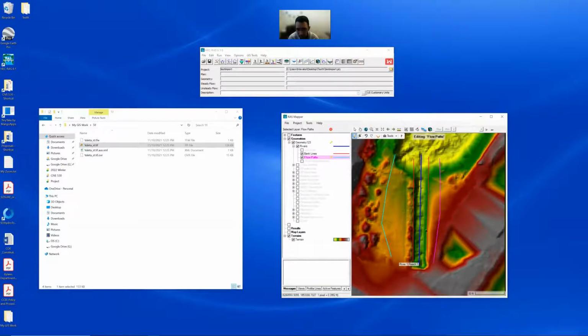And most important thing you can get out of this is your cross section. So we're doing all these to have some cross sections. And the goal is to get that cross section data automatically from this terrain file, rather than just typing station elevation 1, 2, 3 all the way to 100, 200 for a complex earth like this.